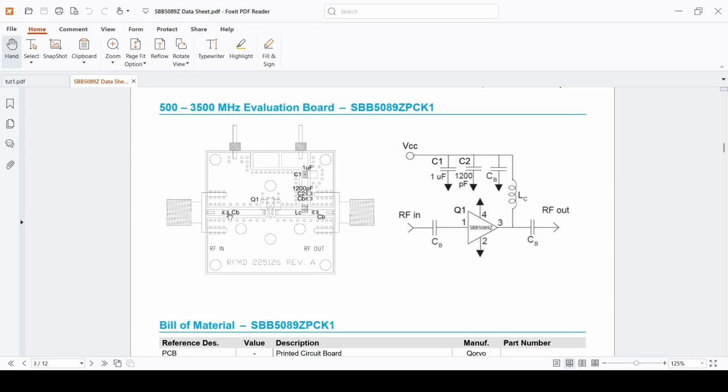Also, these are the capacitors that are used to block the DC coming from the input to the amplifier or coming from the output to the amplifier. And their value needs to be designed for the frequency of our interest, because essentially, since we have a capacitor, and you can assume that here you see a 50 ohm resistance, you will see a high pass response here.